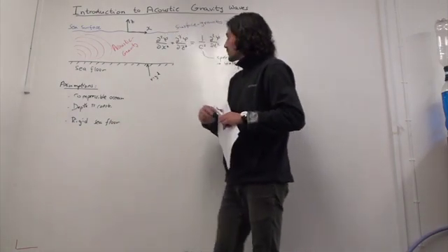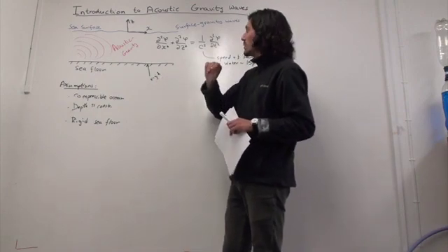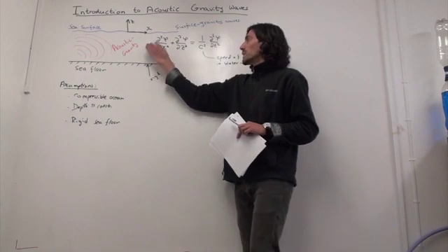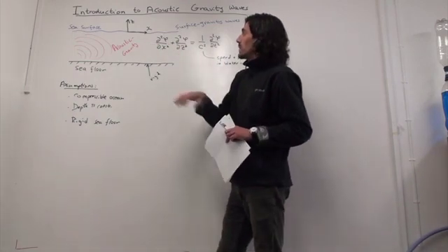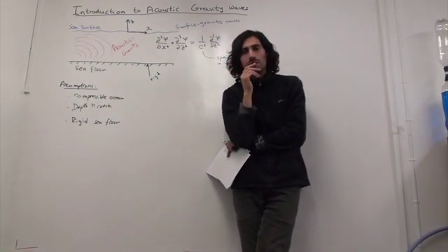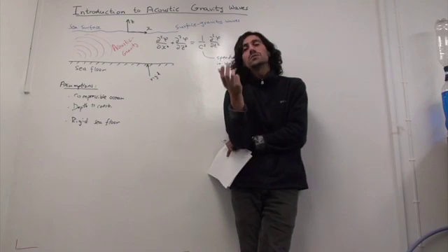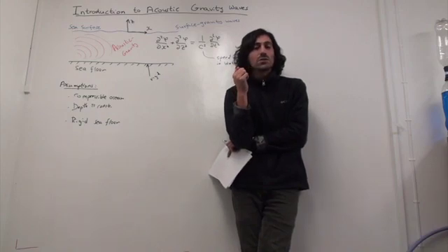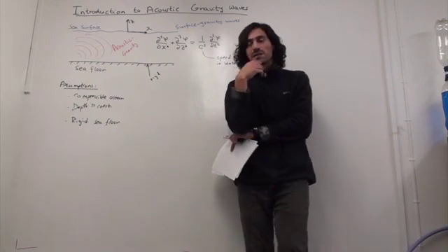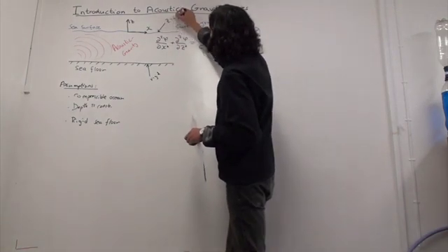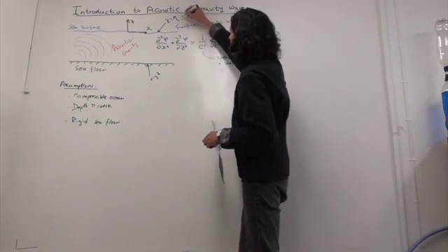I'll type that later on mathematically after I explain about the phi here that is describing the interior of the medium. What happens at the surface? At the surface we have two conditions. At the end of the day, you need one condition, that's the combined condition, and you don't really need to know how we derive it, but I want to give you some idea about the physics behind it. At the surface, the first condition is called the kinematic condition. The kinematic condition says that this is eta, so this is the surface here, z is at eta, and eta is a function of x and t.